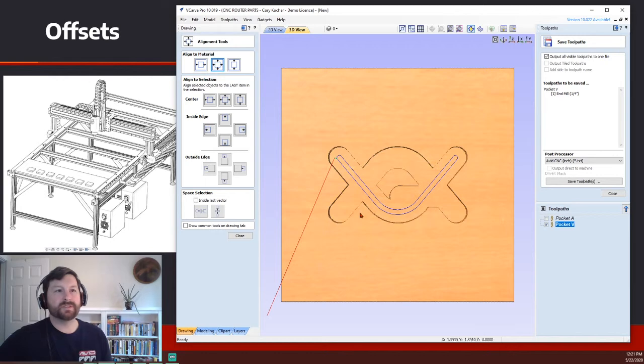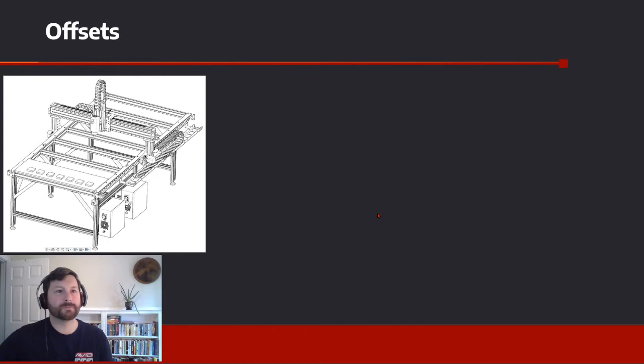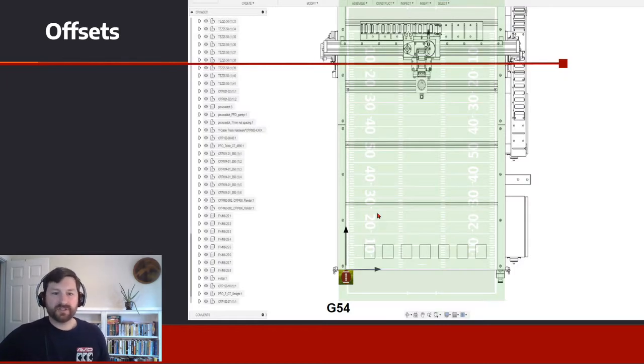Perfect. So I have those two pieces of G-code saved in my folder there. In the first example where we did the 48 by 12 inch piece of material, we had our G54 set in the lower left-hand corner. And generally speaking, for this discussion, the machine coordinate 0, 0 and our G54 0, 0 were the same, right? We were all the way lower left-hand corner of the machine, and that's where we started. And so you would see we would come, this would be our 0 position, and we would run all 7 of those toolpaths, A, V, I, D.